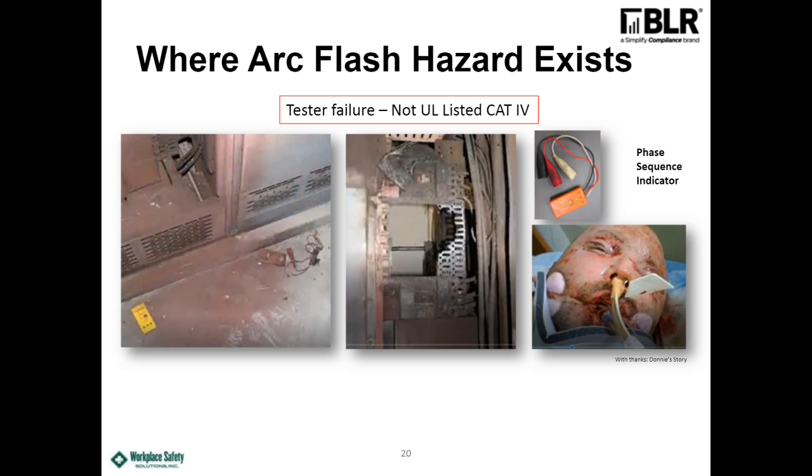So that means the transient is like a spike in the system. It could be 3 times greater than the voltage, for example, and caused it to fail. And once it failed, the air was ionized and changed into a 3-phase fault. And in the picture in the middle, you can see all the switchgear and the bus work and all that stuff just completely blew apart. So it had to be a fair amount of fault current on there to cause that to happen.